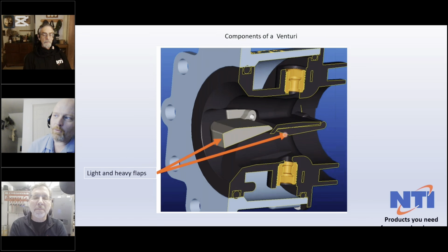The purpose of the light one is it actually blocks this orifice at low airflow rates. And at lower airflow rates, the heavy flapper keeps the bottom half of the venturi closed, which means that the air moving through this part of the venturi is going to move faster, exerting a higher suction, if you like, or a lower pressure on this orifice, meaning that this is then supplying most of the gas flow when the boiler is running at low fire.